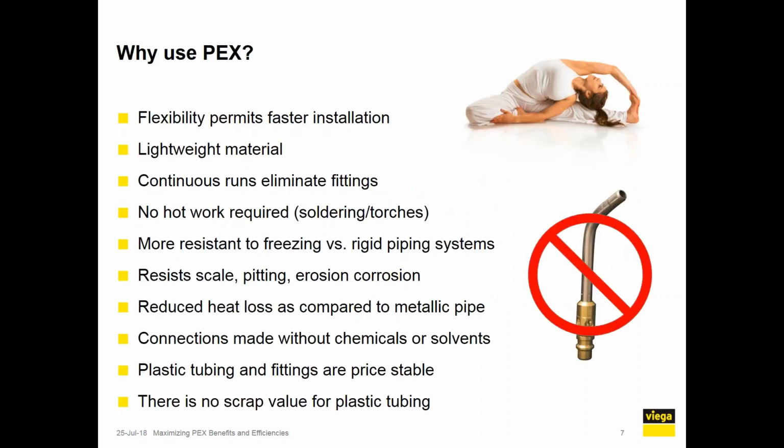So why use PEX? There's several reasons. The flexibility is faster installation. It's a lighter weight material. You can eliminate fittings. There's a degree of freeze resistance, though it's not freeze proof. It has a resistance to scaling, pitting, and erosion corrosion.